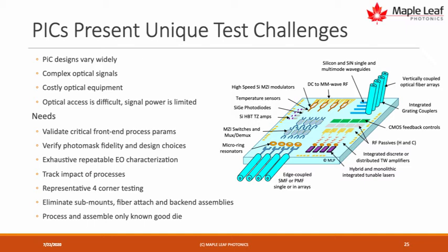The tools that we've described already provide that, and by being able to make measurements throughout the cycle of wafer fab, back-end process, singulation, sub-mounting, and eval board, and making the same kind of measurements throughout that chain of activity, you can get a great insight into where stresses are coming up, where aging effects or humidity effects are having a problem. And so this is why these types of tests give you insight that is very difficult to get otherwise.